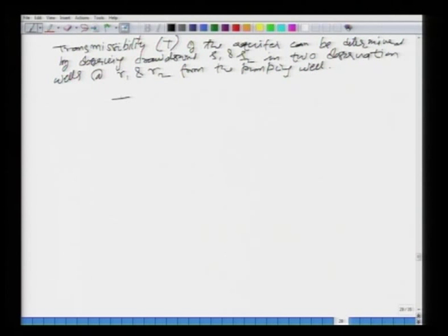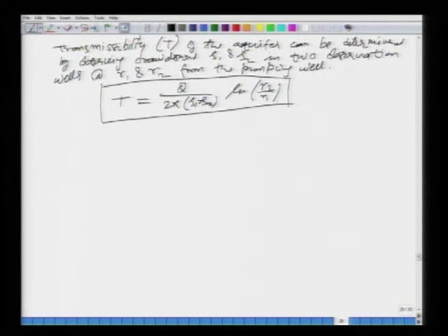Okay. So that your expression for T then would come out to be Q over 2 pi of your S1 minus S2, this is from equation 2 actually, and then natural log of R2 over R1. Okay. And you can use the well and the radius of influence also, okay, and you can put the things accordingly. Okay. So, this is your equation number 4. So, you see that the case of confined aquifer with steady radial flow towards the well can be used to determine or estimate the aquifer properties.